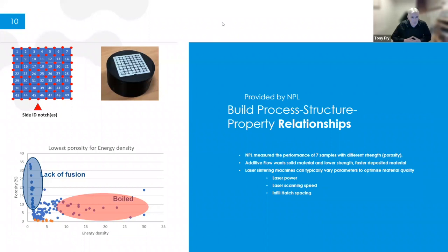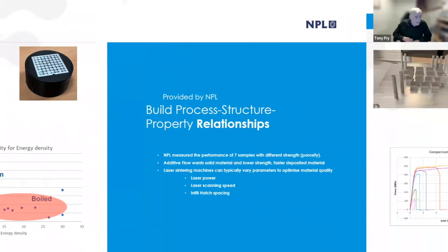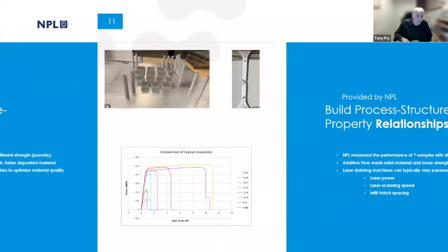We actually used 3 of these, so there were 49 different processing conditions per block. They're about 25 millimeters by 25 millimeters square. We then used a combination of optical microscopy, scanning indentation, microhardness measurements, and after that, impact excitation to look at what the actual properties of the material are. You can see in the plot there, oh, too fast, back one.